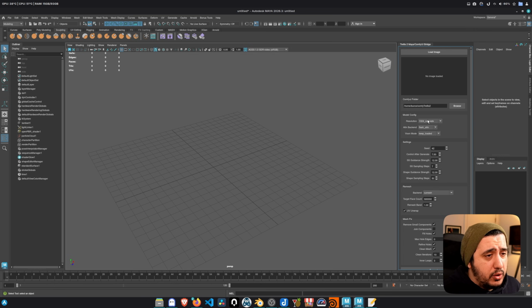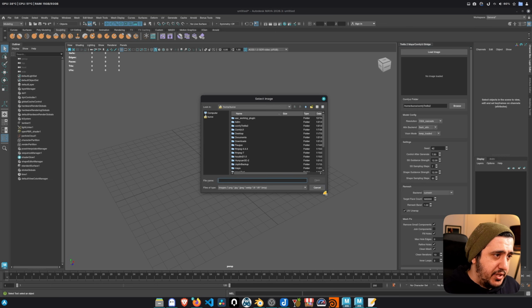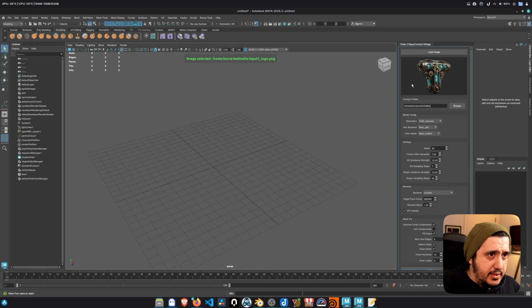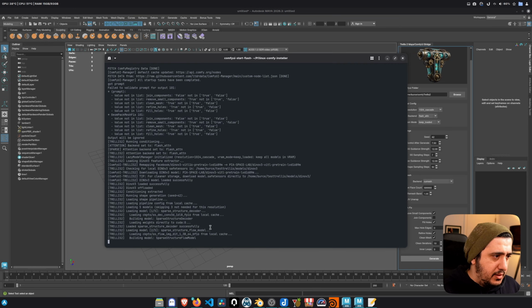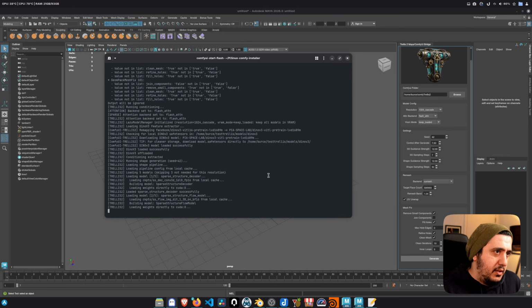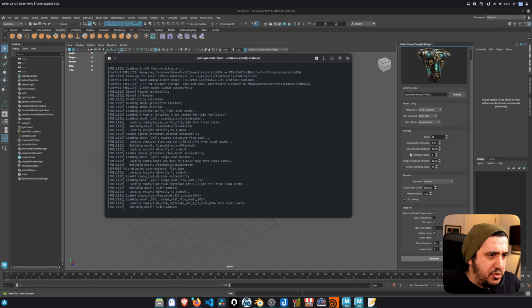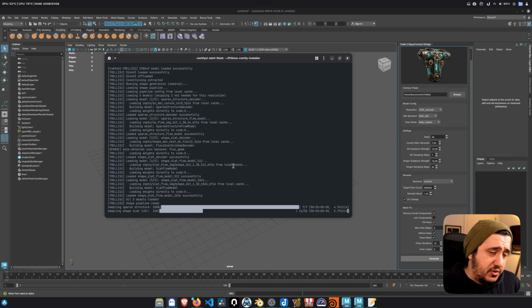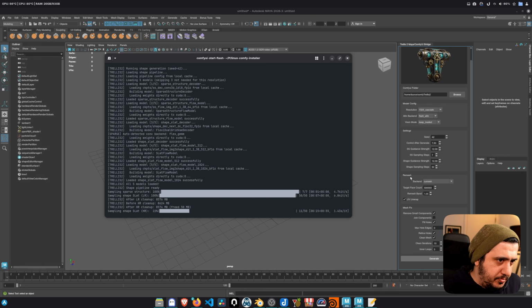We have all the node properties defined here: resolution settings, remesh settings, mesh fix settings, and it is asking me to choose an image. So I can go to my input folder, select this and generate. Let's look at our ComfyUI logs. It is generating. I am not using crazy sampling steps here. I want it to be fast and I am meshing it with a lower triangulation amount. Yeah, I should set this lower.